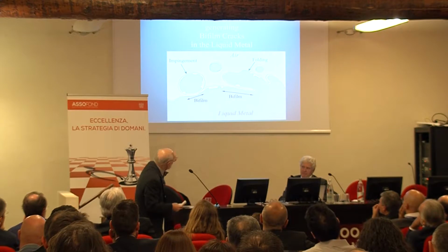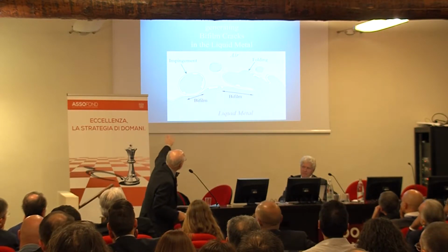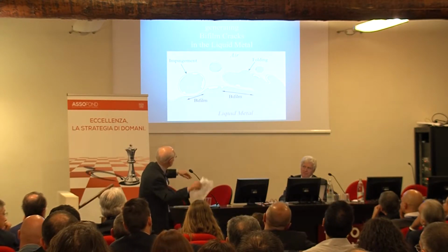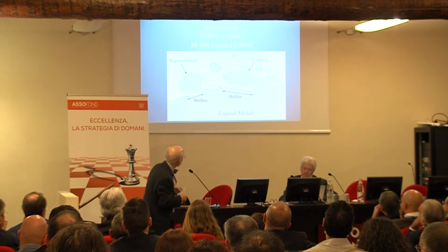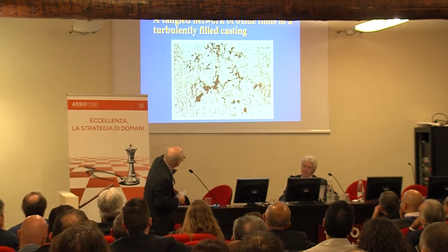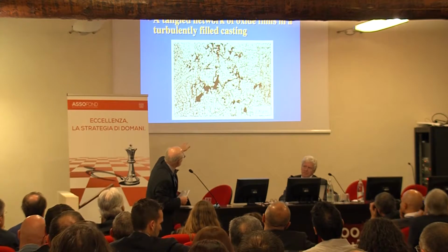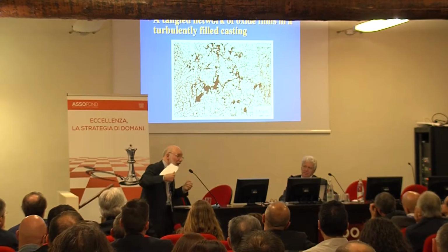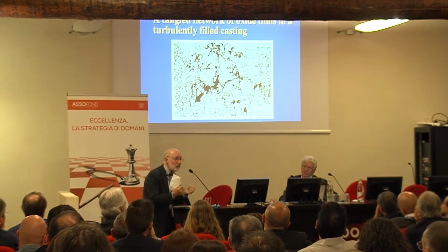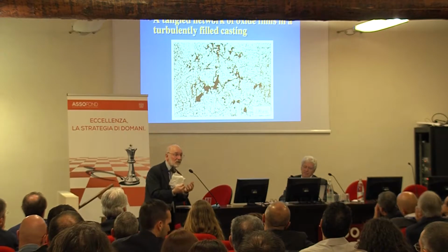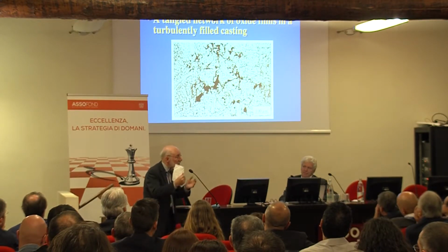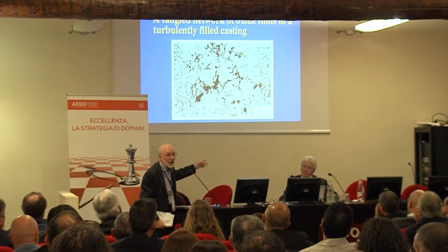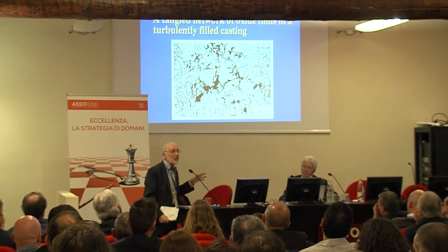So here we are. We're making bifilms by surfaces just impinging or by surfaces folding. And in the next slide, we can see something in aluminum, and those pores are air bubbles. Once again, they've been hammered in different directions, and they've got a rigid outer shell, which is the oxide, which means they don't keep the nice spherical form. Here you can see the bifilms because these happen to be very thick. Normally, you can't see them.